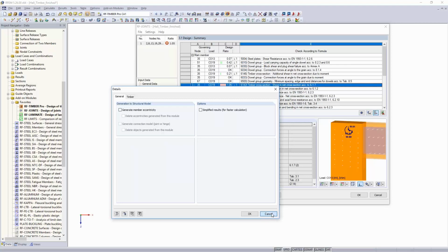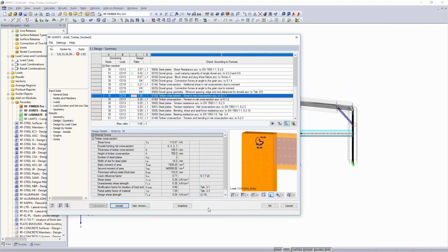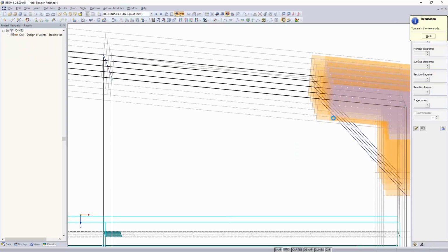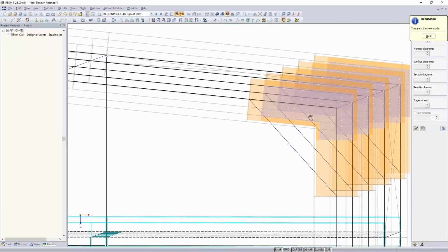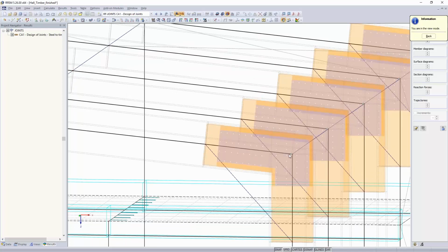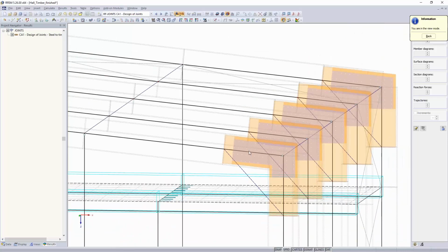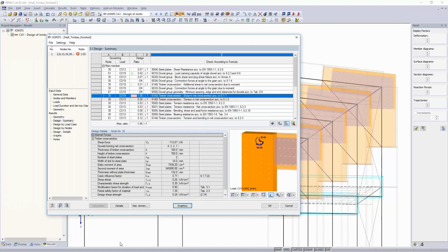Right now, when you look at the structure, we can do that in here. There is still this connection assigned, okay, for sure. But it is still this moment hinge here with a value of 0, and this member is connected to the corner point. But if you look at that in more detail, you would say that it's probably connected via all the dowels, and here is actually no connection. So the static system that we are designing in here is actually wrong.